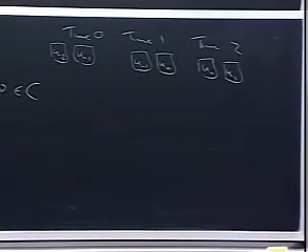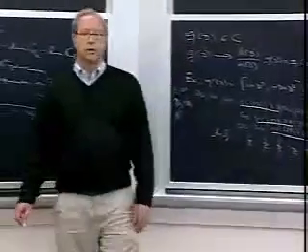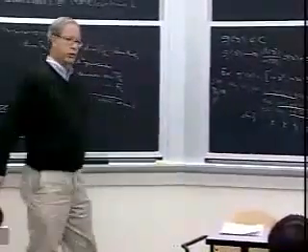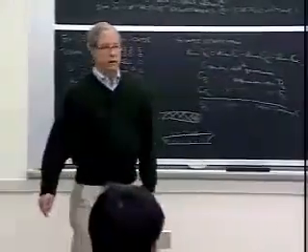Exactly the same theory goes through for rate 1/n convolutional codes. I will tell you briefly that to treat rate k/n, it's basically the same thing, except we need k generators starting at each time. To get a canonical encoder, we just get a trellis-oriented generator matrix again.